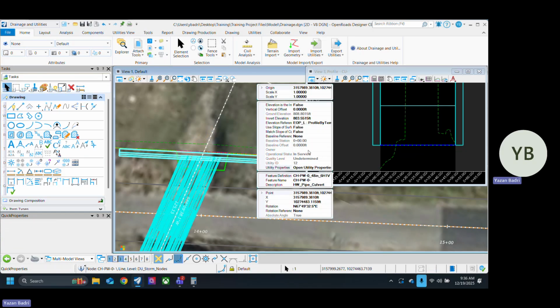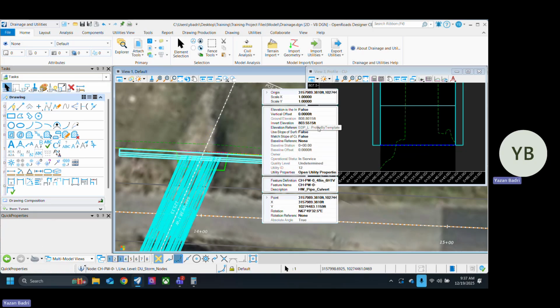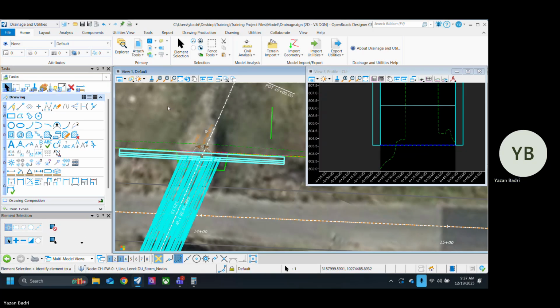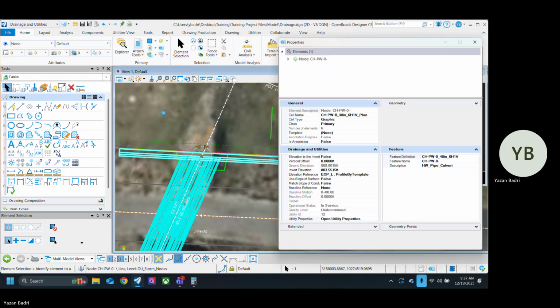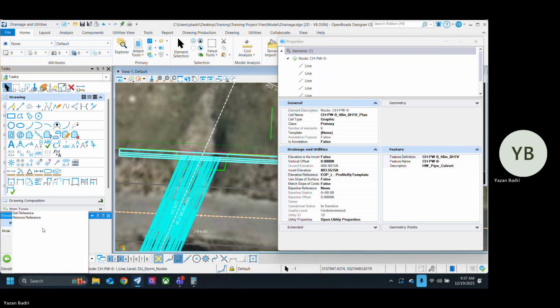Sorry, I got kind of pulled away on something. Is there an issue right now with the conduit? It's not letting him update the flow elevation. Yeah, and I think the reason is it has an elevation reference. So it wants to keep the same height of the wall, but it's tied to the edge of pavement, so it's not letting me change that. Just doesn't want to. So is it better to draw a MicroStation line and reference that instead, so you have the freedom to do it?